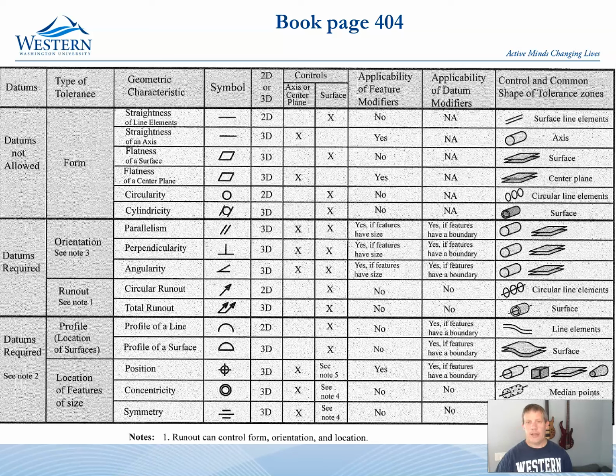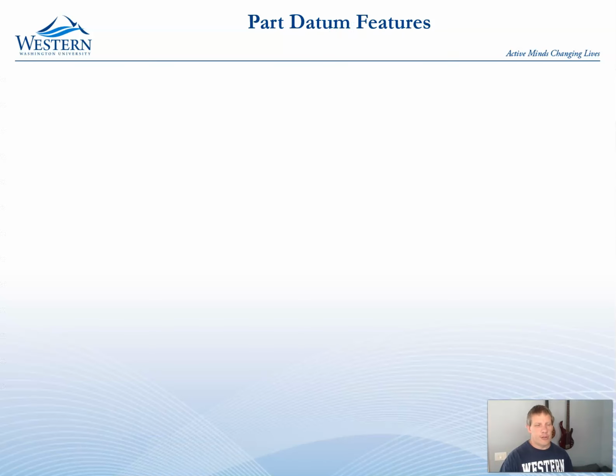Another way to do it would be to use a tool that helps you. For instance, the FTA workbench in CATIA will help you with that. Now, I have found the FTA workbench to not be 100% accurate, and it will let you delete or add datums that should not be there. So be really careful about that. No matter what you're doing in CATIA when you're putting these in, don't add or delete them. Make sure that you use the right numbers.